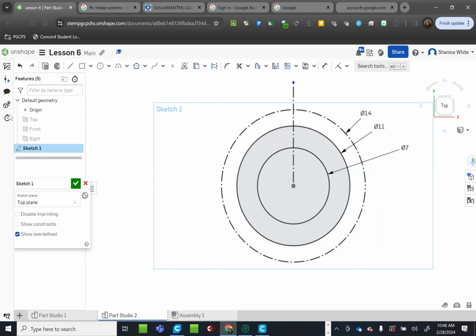After I have that, we have this little notch. I'm going to create 2 circles for that. And notice that I hovered my mouse right where this construction line and that construction circle are. And dimension these to 4 inches and 2 inches.